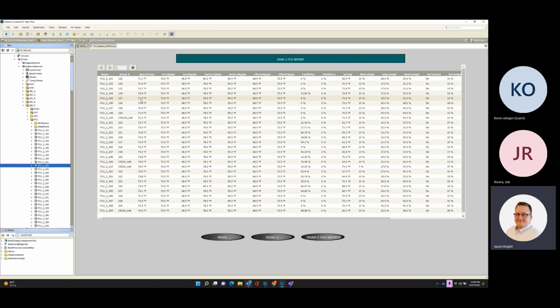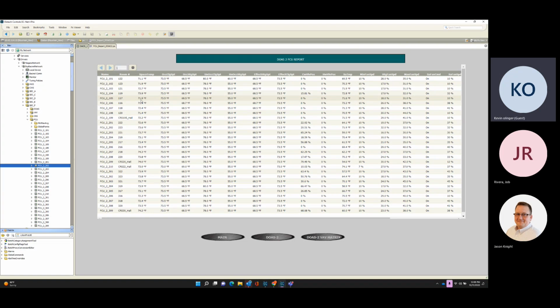And if it's 80 degrees in the morning when these start, 2 valves open, the chill water system is indexed on, the chillers are going to try and make 44-degree water. So they may stage up to 60% or 80% or 100% before they get down to pull all that piping water down to 44 degrees. Does that make sense? Yes, thank you. And so that is essentially 2 zones in the whole building or per Jace? The whole building. Okay.